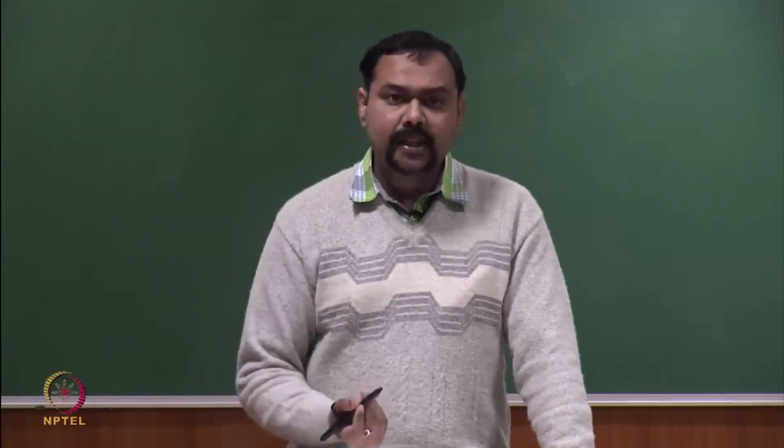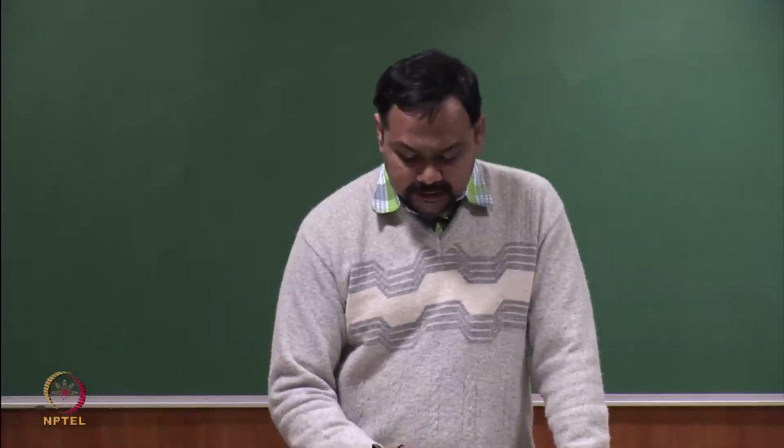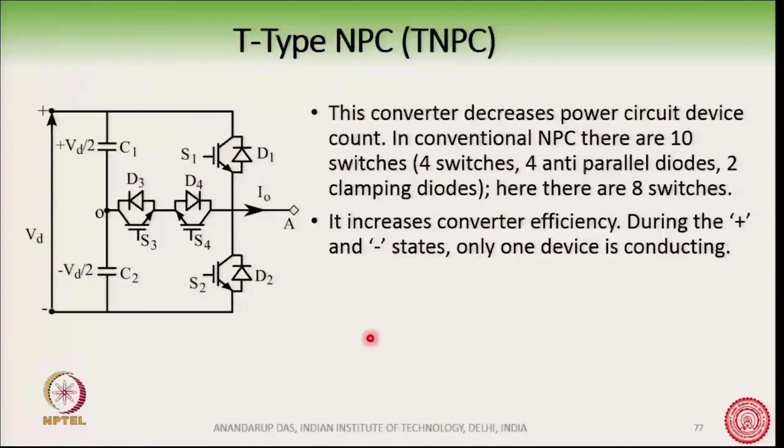You can easily understand, when you have the plus and the minus states, then only one device is conducting in this topology, whereas in a 3 level NPC during the plus and minus states 2 switches are conducting. So, therefore, it has been reported that TNPC actually increases the converter efficiency. We will again not go much into detail about the operation of TNPC, and interested viewers are requested to see additional reference material.